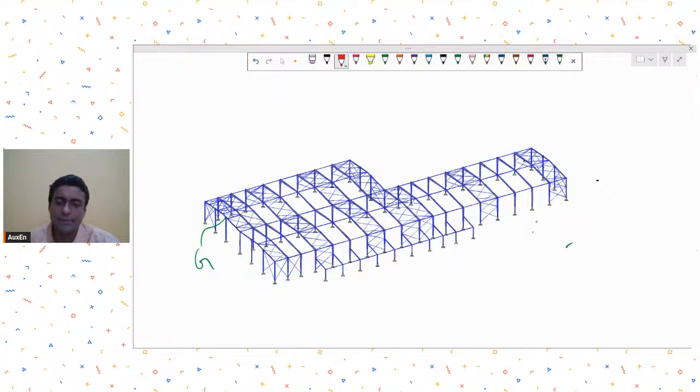compression only for lateral loads and no compression for gravity loads, and then you can assign that these members, let's say, will take compression, okay, for lateral loads, and then these bracings will not be effective at that time. Maybe you can do such a thing, or maybe what you can do is just take this out, just take